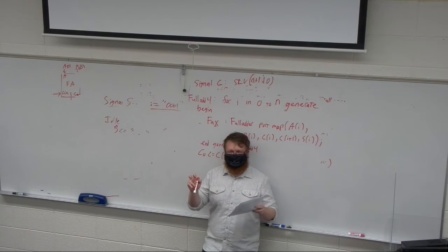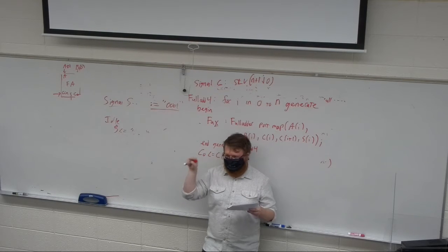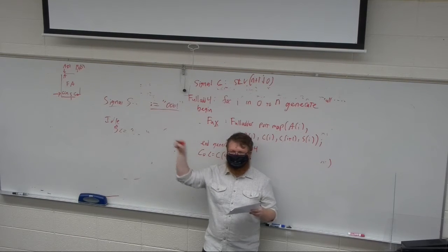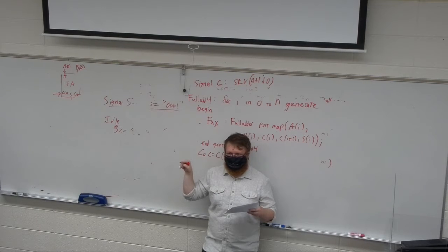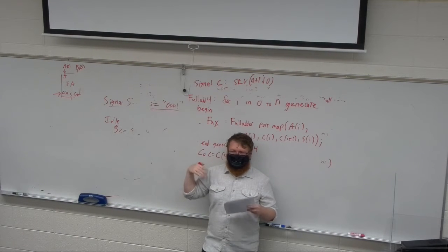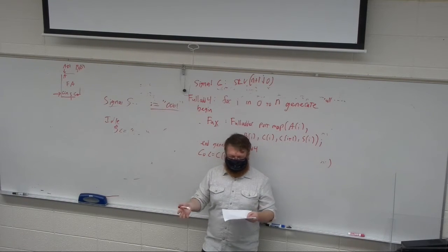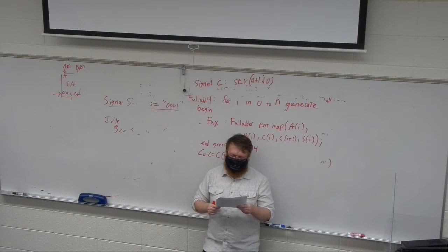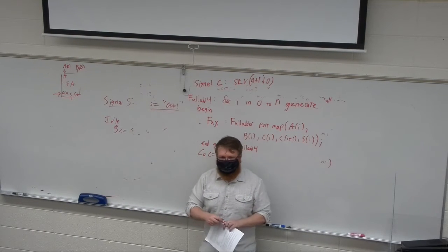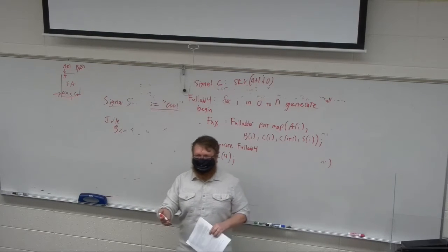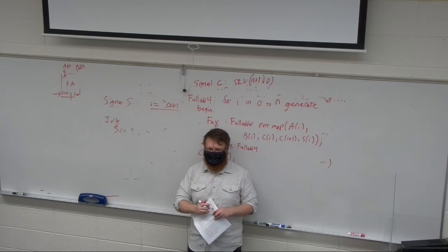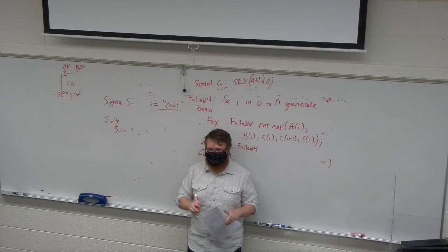The correct way to do it is, inside of the module it had a port called status, but in the port map, I didn't list it. So all you would have to do is add that line that says status and then map it to status lights and correct the number of bits. That would have been the easiest way of fixing that. There are other things that you could have done, just use status, but that was the main one. That may have been the trickiest one to catch, because not everybody can yet realize that I don't need to call out all of my ports in an explicit port map. I can just leave them off, and it is okay with that, as long as they are outputs.